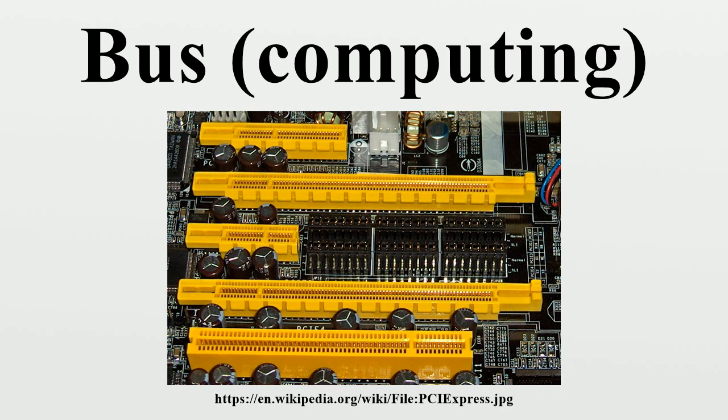Implementation details. Buses can be parallel buses, which carry data words in parallel on multiple wires, or serial buses, which carry data in bit serial form. The addition of extra power and control connections, differential drivers, and data connections in each direction usually means that most serial buses have more conductors than the minimum of one used in 1-Wire and UNI/O.